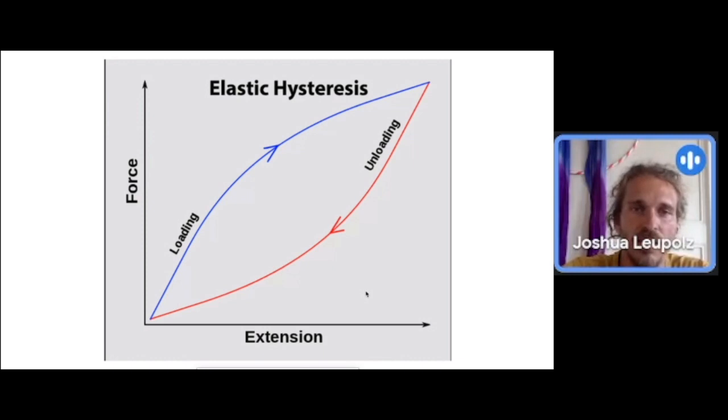Let me just check the next graph. This is pretty interesting for us. This curve can change depending on the speed, how fast you're loading it. If you're loading it relatively slow, the whole graph will stretch out to the right side a bit. So if you're going to the same force and holding it for longer, it will stretch out more over time. And then detensioning, you have the same effect.